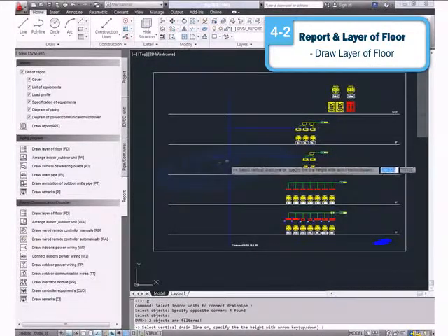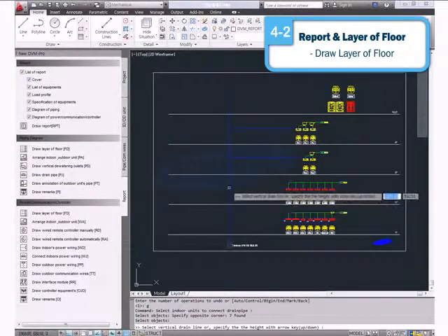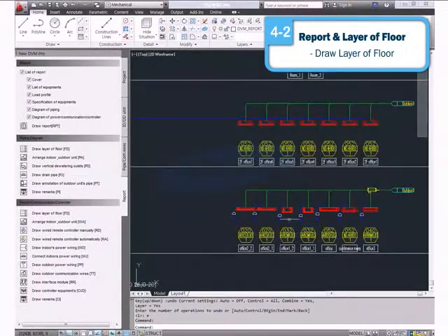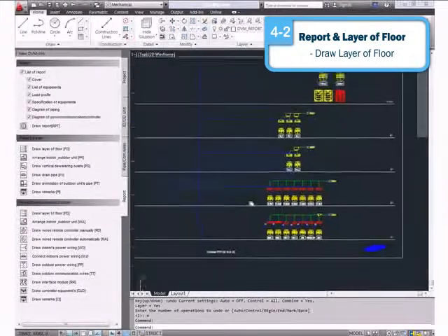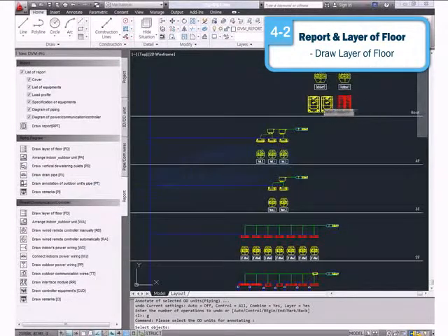When the small square box type cursor appears, move it to the vertical piping, and click the mouse. You may press the up and down keys on the keyboard to adjust the height of the piping. For the floors with dewatering outlets instead of the vertical piping, drain piping will be connected and displayed on the indoor unit of the schematic diagram.